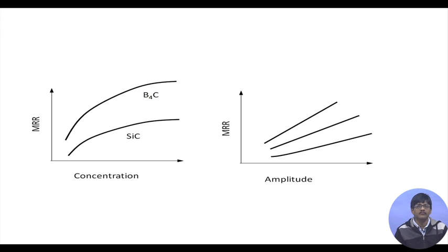Amplitude. MRR has a relation with the amplitude; MRR is proportional to the amplitude to the power 3/4, and that is what is reflected here. If the results are taken more towards the higher values of amplitude, surely they will show a tendency to have less gradient.